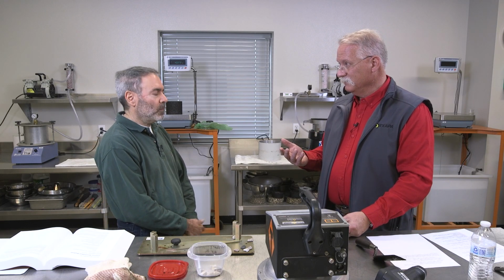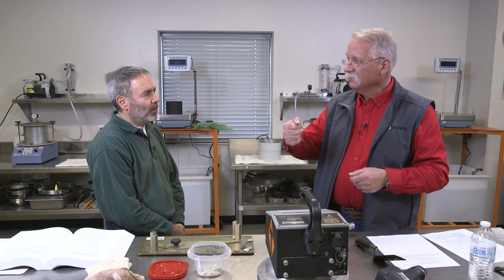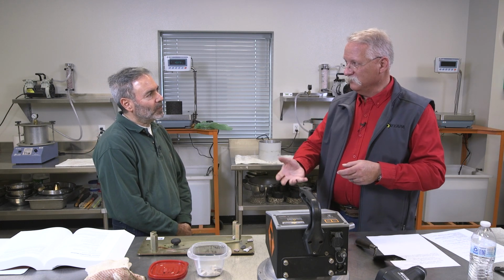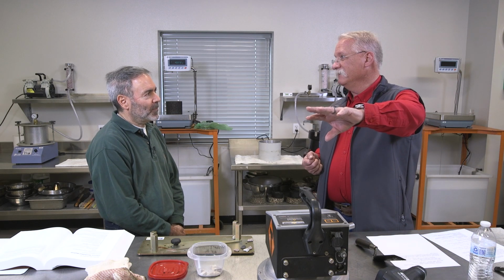That doesn't seem like a lot when you've got, what's an extraction, 2,500 grams? Yeah, somewhere in that range, 2,000 to 2,500. But most of that stuff is fines and asphalt. A disproportionate amount of that material is fines and asphalt. So if I'm scooping my material out and I'm stripping out asphalt and fines, and then I run my test, well, now my test is actually off a little bit. There's less asphalt in there.